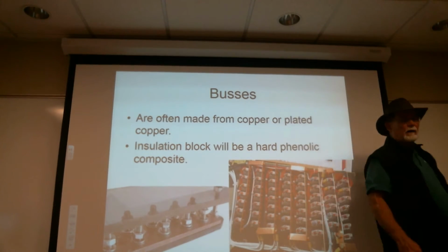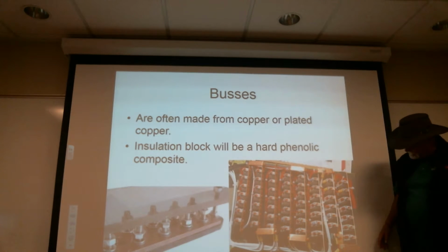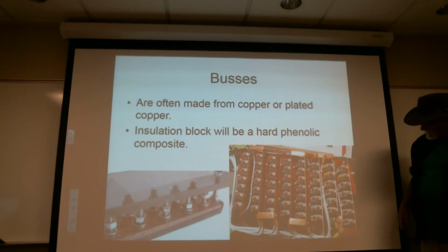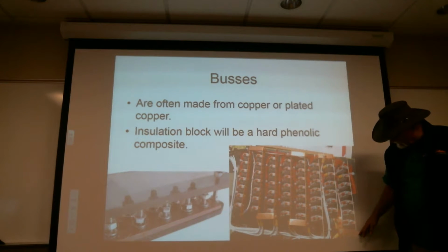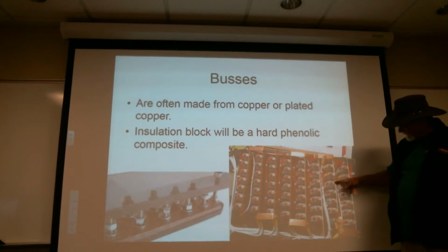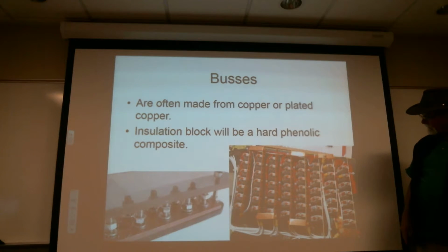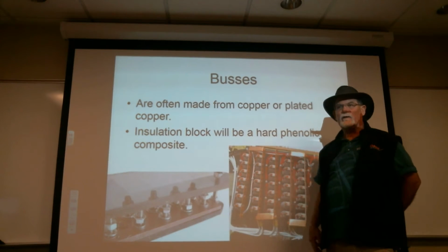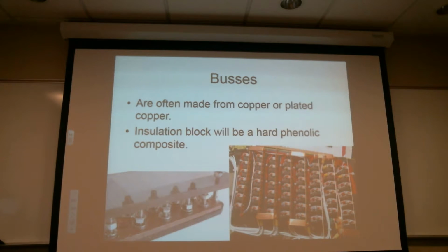Here, whoever's building this, they did a very nice job of keeping everything nice and clean and concentric. What they did is all power distribution comes in on big white leads and everything goes out on red. They said, all right, we're going to have a big lead come into here, or maybe it's this one coming into here, and we're going to apply power to this copper strip, which is attached to each one of the circuit breakers. It's going to jump across to each one of these circuit breakers, and note it doesn't go anywhere else. Then there's another one that's just this bus here, and another one that's that. So this actually has 3 independent buses in there, and they've used copper strips to directly interconnect all of those circuit breakers together. Okay. That's a pretty clean installation.